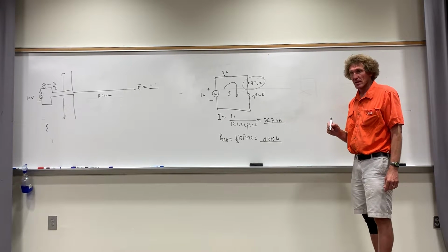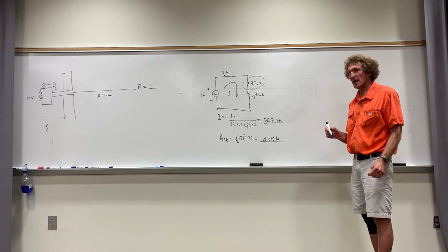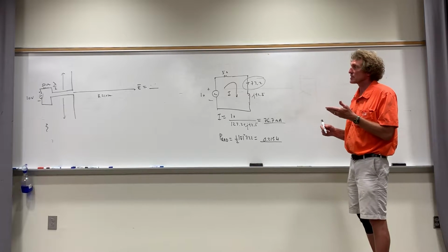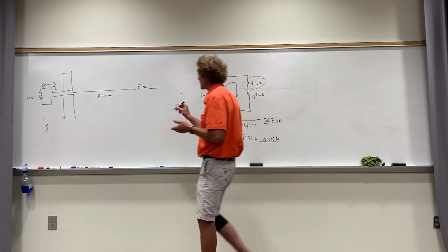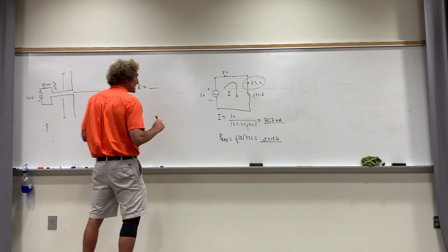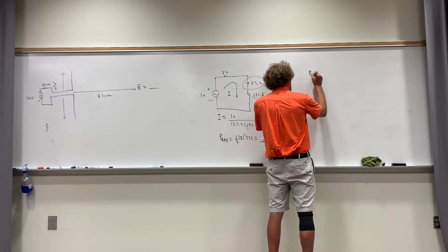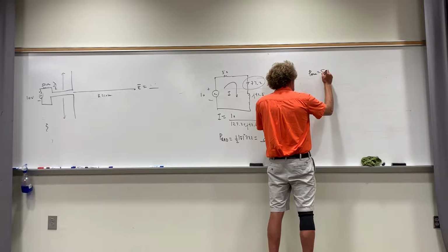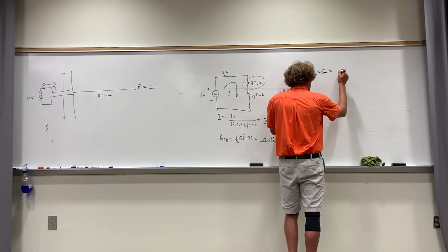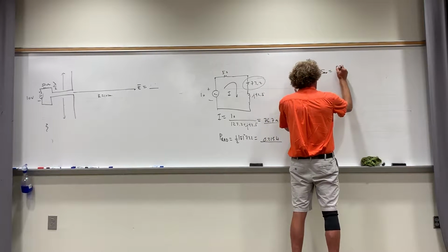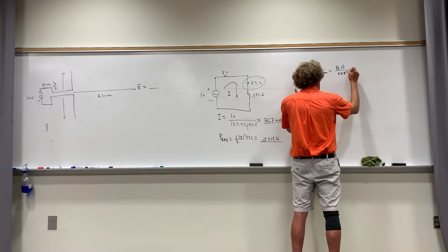Okay. Now that I have that, I can easily get the power at this point, because now I know the average power density, P av at a range, which is really my S av, is equal to the transmitted power times the gain over 4 pi R squared.